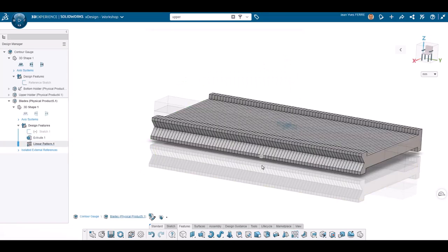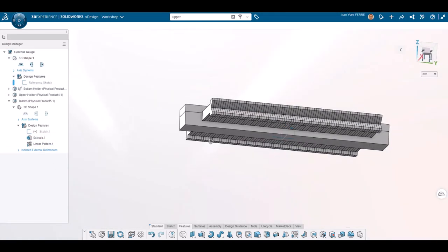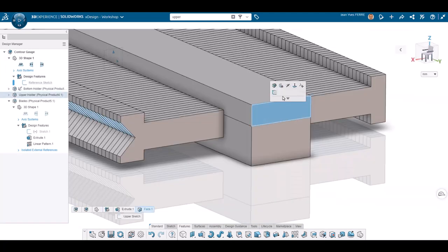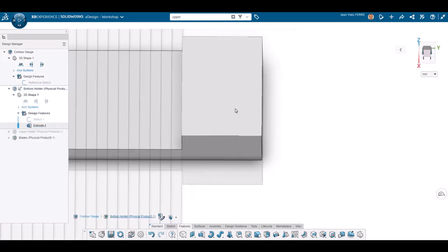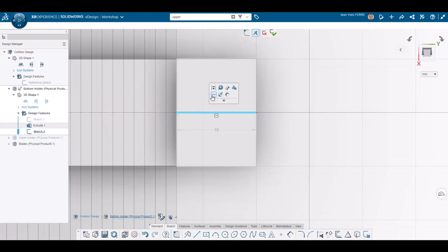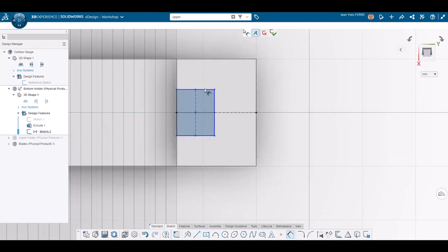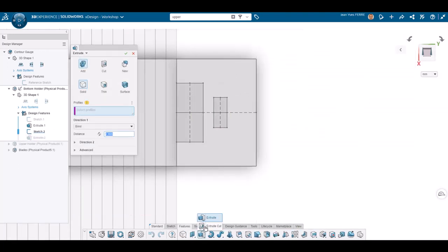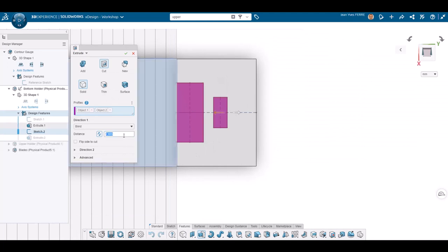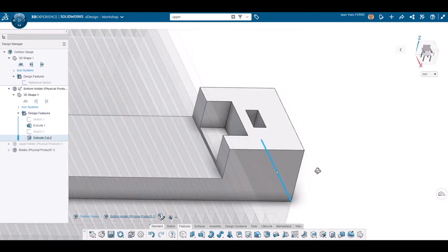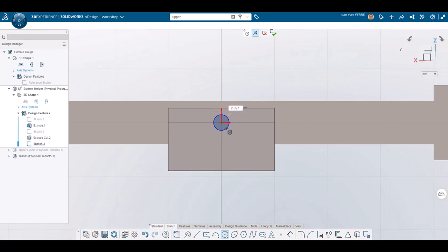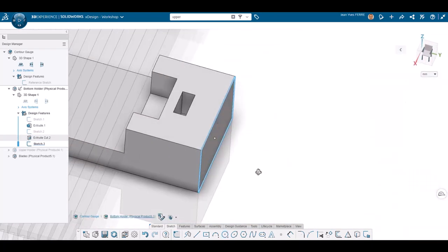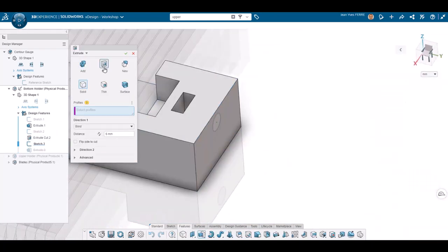I now create the blade clamping system in the housing parts. There will be a cavity for a nut and a cavity for a pressing part. I made the cavity so the nut cannot turn. It will be easier to fasten the knob. I then create a hole for this bolt, and selecting the end face will cut all the material I need to remove and no more.